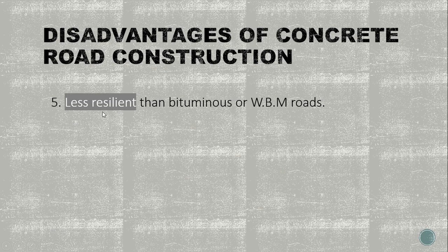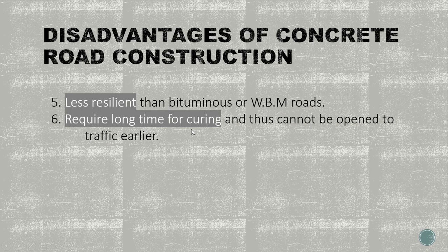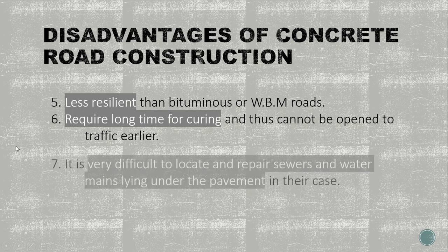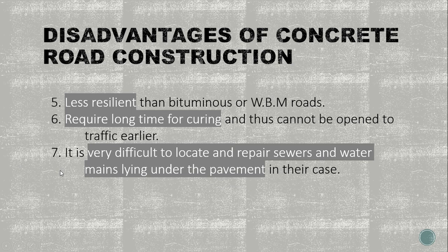Less resilient than bituminous or WBM roads. It requires long time for curing and thus cannot be opened to traffic earlier. And it is very difficult to locate and repair sewers and water mains lying under the pavement in their case.